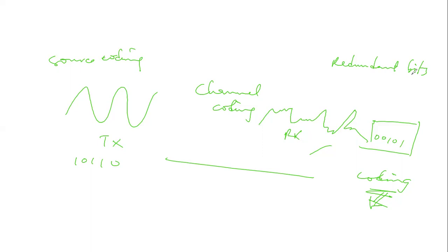Shortly, you see that block codes are memoryless codes, and we can use combinational circuits to design them. Okay, you know combinational circuits, isn't it? Your normal AND gates and all of that. But your convolutional codes, they have memory. So since they have memory, in terms of practical implementation, we can use sequential logic to design them. And you know examples of sequential logic devices, your flip-flops, right? So with your flip-flops, we can design convolutional codes in practical terms.